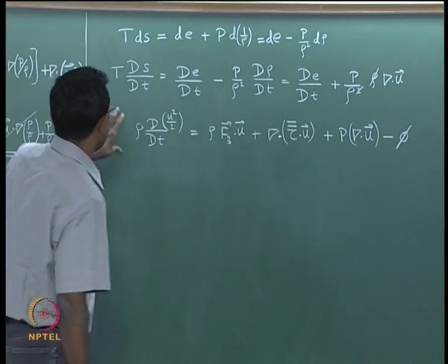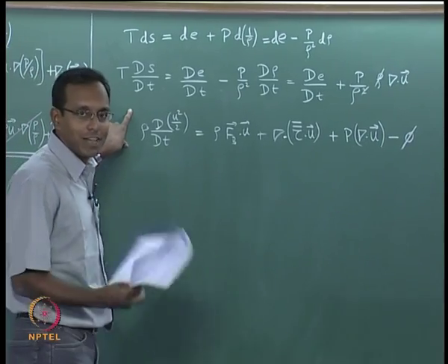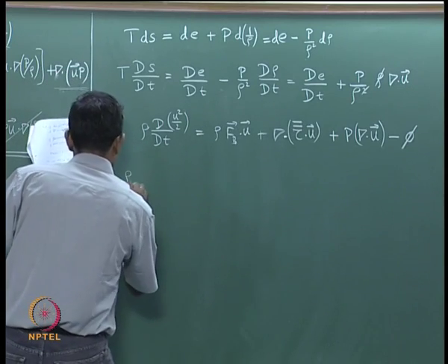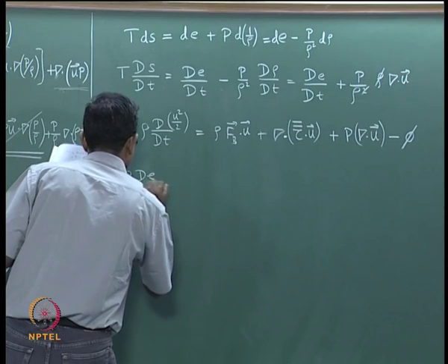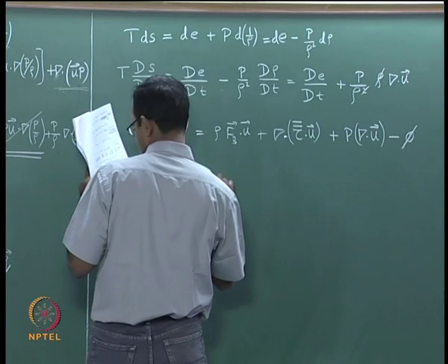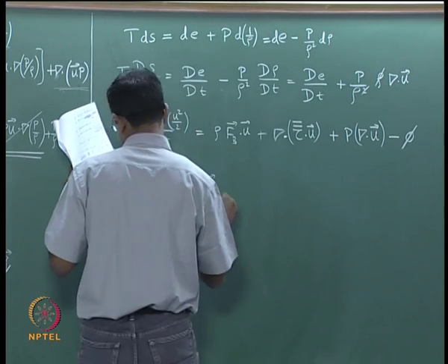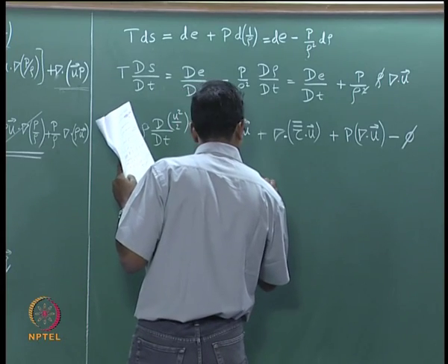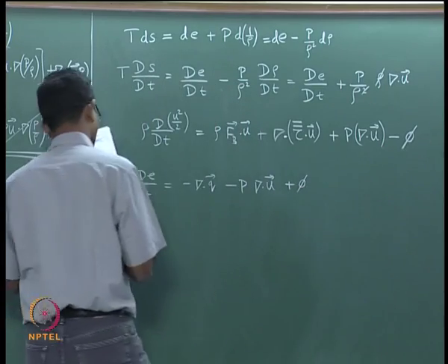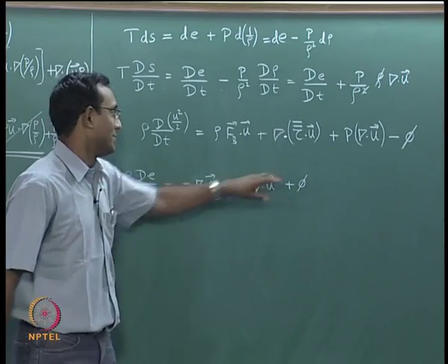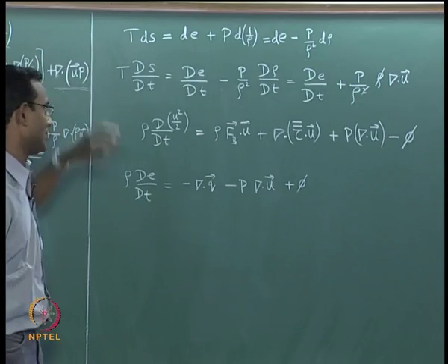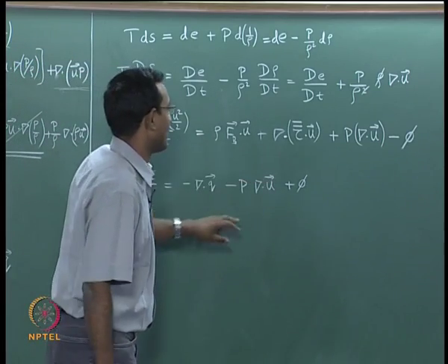So, if I subtract this from our original energy equation which we had before, then it comes to a point where I can write it as rho dE by dt is equal to minus del dot q minus p times del dot u plus v. Only these will be remaining. You will find that the viscous work is going to be internal and it will just sit in the total energy also. So, the only thing remaining is this particular part.